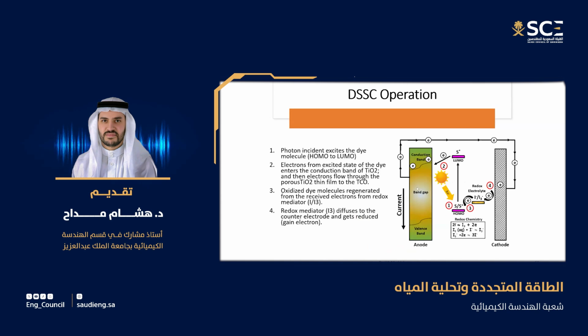If you look at the physics behind it, what is happening here? In this type of system, I just tried to give notation here, 1, 2, 3, 4. Look at the notations or the numbering. 1 means that the electron is going to be in the dye itself. If you look at the purple color, the dye itself is going to be excited, with that electron inside the dye going from the HOMO level to the LUMO level. These are the abbreviations of the energy levels.